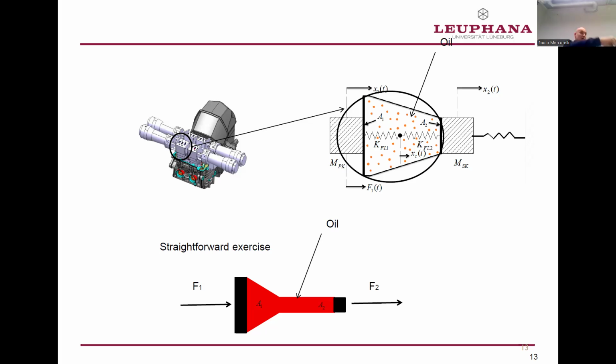Exhaust was connected with the cam, and the intake was free. The idea was to mix fresh air with combusted air, but just controlling one valve, the intake valve. In German, Einlassventil.